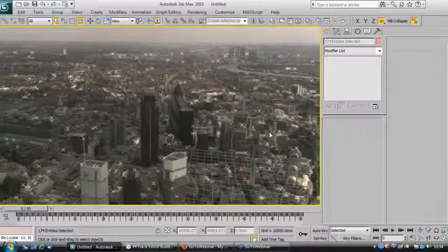It does appear that everything seems to be in the right place, which is a huge relief. So that's the more traditional method of camera matching using user features, auto features with an auto track, doing a little bit of cleanup for those tracks, and then solving the 3D camera. And then we've had a look at orientating our scene very briefly and scaling that too.